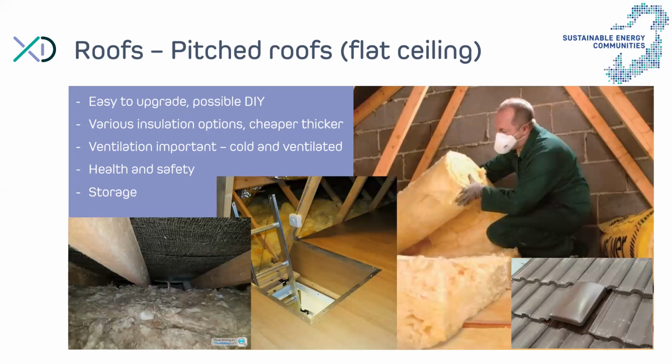But what's important to consider is that when you're increasing the insulation at ceiling level, you're preventing heat from migrating into the cold attic, and any vapor that goes through the ceiling and through the insulation into the attic, which is then very cold, can condense and create water accumulation, which not only reduces the effectiveness of the insulation, but also can cause rot and mold within the attic space. So it's very important to ventilate the attic properly, and to make sure that air can flow relatively easily along the eaves of the house.